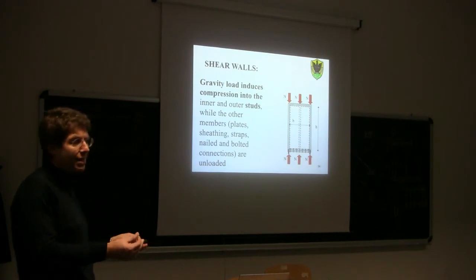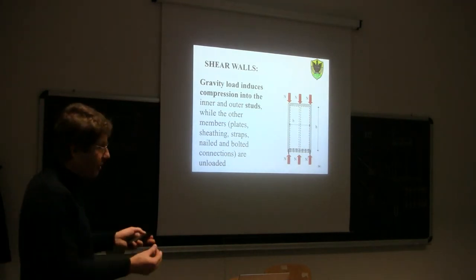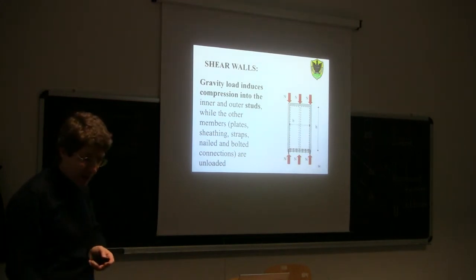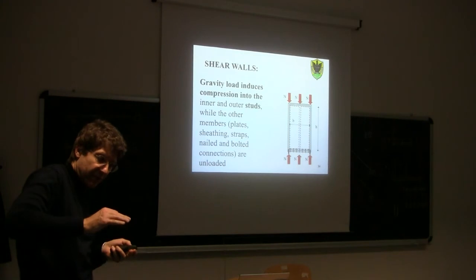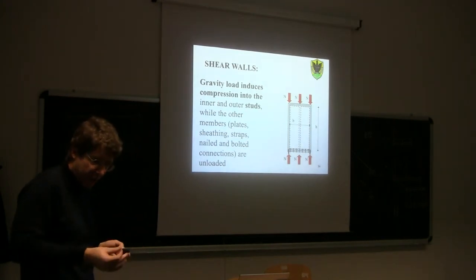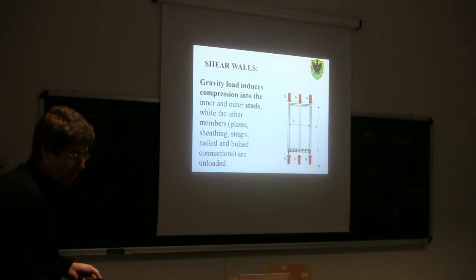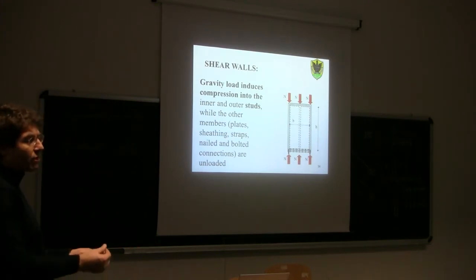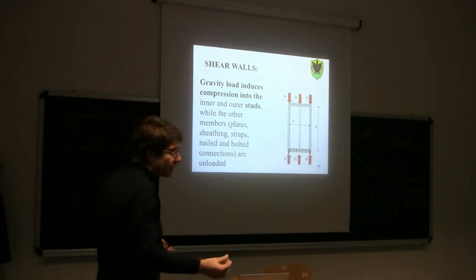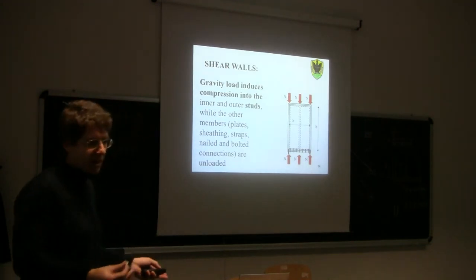We cannot say it prevents buckling, but if this member wants to buckle out of plane, it will also have to deform the sheathing out of plane and the connection itself. But the stiffness out of plane of this sheathing is much lower than the stiffness in plane, so there will be a contribution, but being much lower, we can conservatively neglect it.